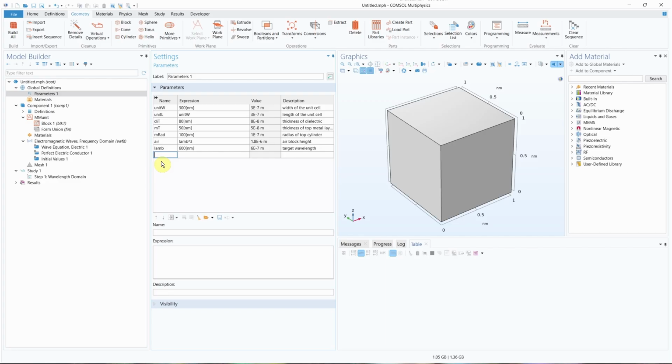So yeah, the reason I do that is we want to have a port later on. So we're going to have a place where light comes in, interacts with our metasurface, and then will bounce back out. And so we will collect information both for the input and the output at that port. And we want it to be several wavelengths away so that we get that far field effect, because in our case, for this particular application, we are wanting a far field effect. If you wanted to look more near field, maybe you wouldn't need to worry about this. But for the moment, we'll keep it there.